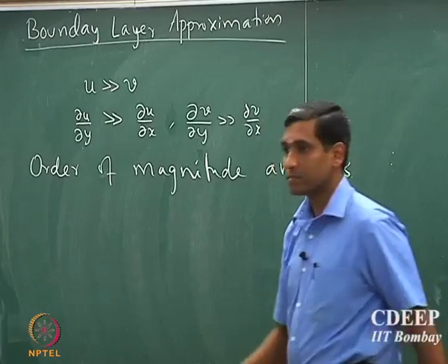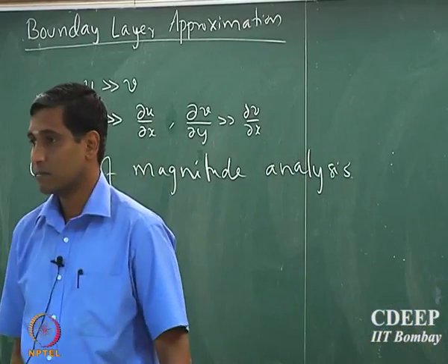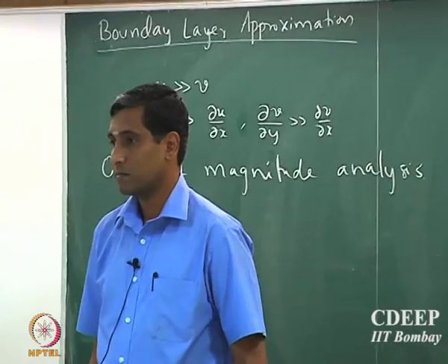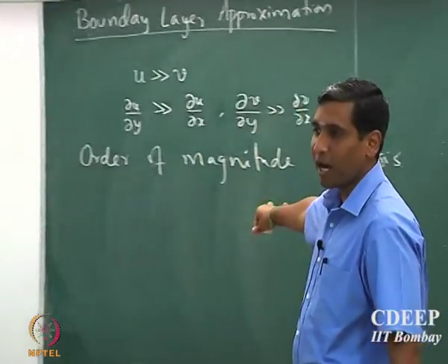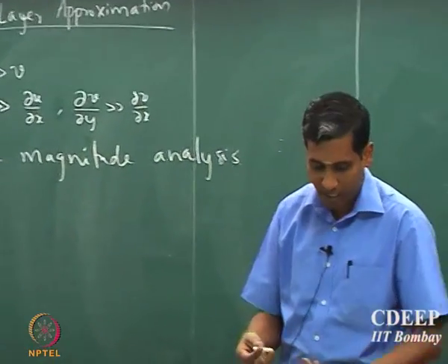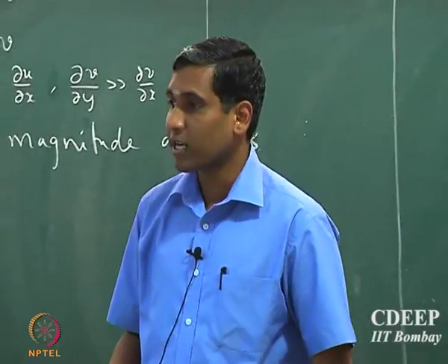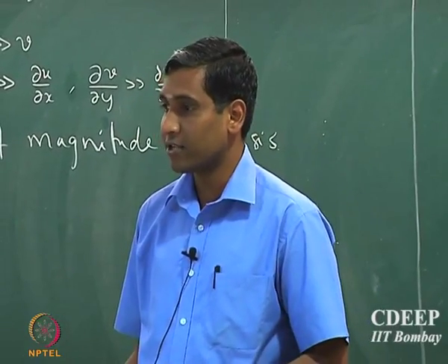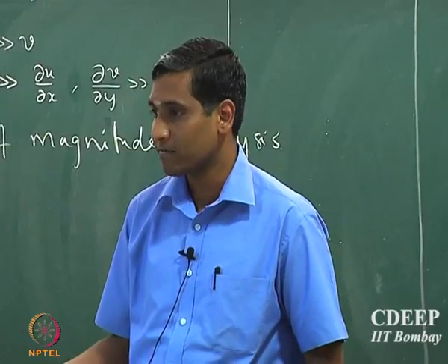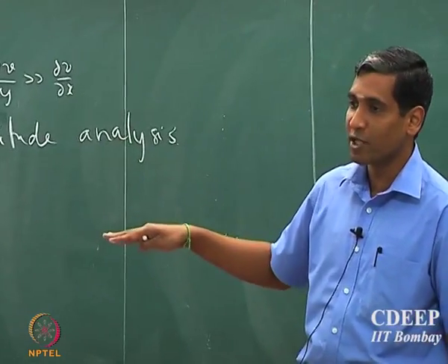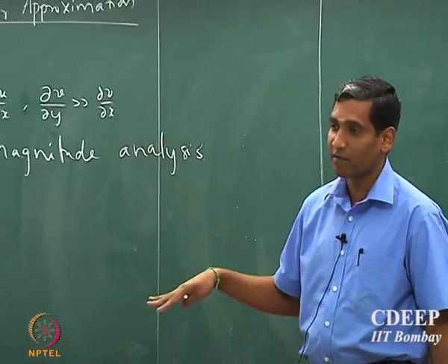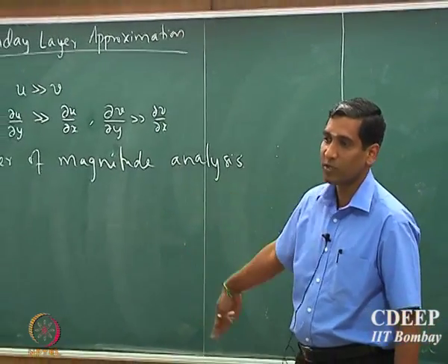Let us assume for now, you will actually see it, if the forced convection flow rate is significantly larger, then body forces don't play much role here. So we will actually see that. Body forces play an important role when you have natural convection, not in these kinds of forced systems.